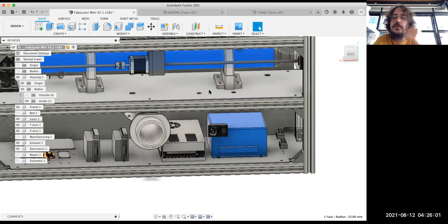And what happens is that if you don't use shielded wires and you don't put the wires far away from each other, you make the wiring correct, then your machine is never going to fire. Every time you try to fire the laser, the controller will simply reset. There is too much noise in the communication, and then the microcontroller, boom, it resets. Or you have jobs launched for 1 hour, and then they stop and you lose the entire job. So this is something critical.